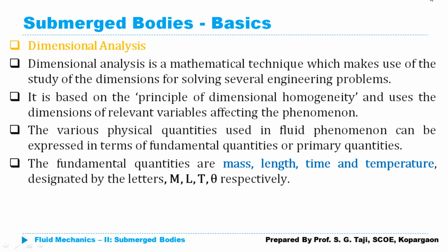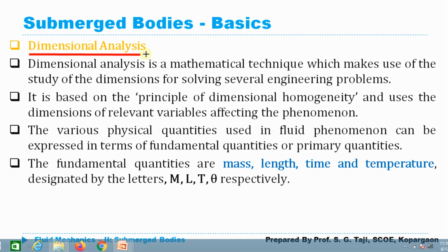Next concept is dimensional analysis. As we all know, dimensional analysis is the mathematical technique which we generally use to solve many engineering problems by using some fundamental quantities. We generally make use of those 4 fundamental quantities, and we write all the equations in terms of those quantities, which are generally known as secondary quantities. So our primary quantities are mass, length, time, and theta.